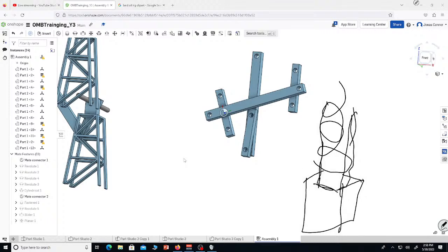What I'll do is have a slider mate so that as it moves down, it'll rotate. Or not slider mate, the screw relation. As it moves downward, it'll rotate. So that just lets you simulate that a little bit better. You can create your own custom cam, I guess, or something like that with it. Make a CNC machine or whatnot. Linear relation makes it something aligned.